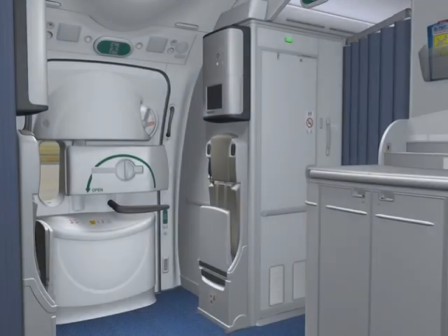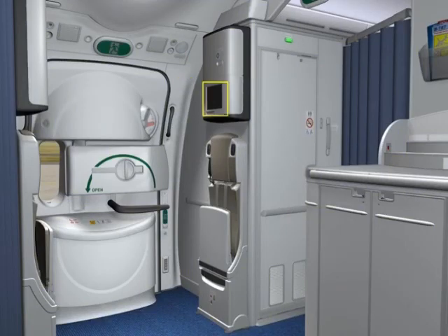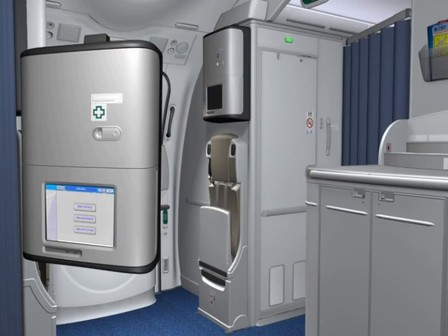The CAPs are in the modules above the attendant seats. All CAPs are the same part number and operate the same. You can change the software to let a panel control all or some of the cabin zone areas. This panel is at door 2 left.